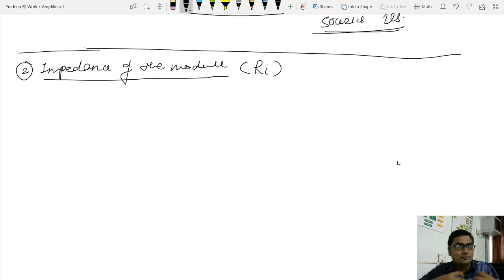Now we are calculating those parameters for the transistorized hybrid module, because if I understand the transistorized hybrid module, then by inserting 2 or 3 capacitors and resistors, that is biasing resistors and some coupling capacitors, it can become an amplifier. The transistor module can become an amplifier by inserting 2 or 3 extra resistors and capacitors. So that's why first we are trying to understand the equations of those parameters which are actually related to the amplifier.